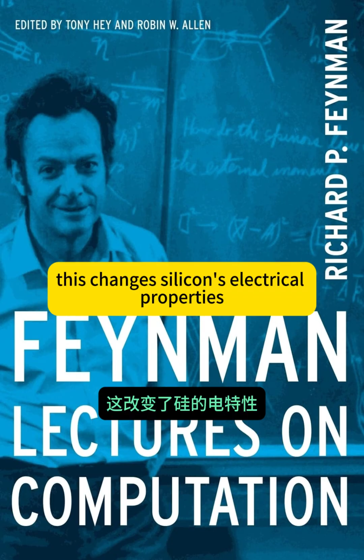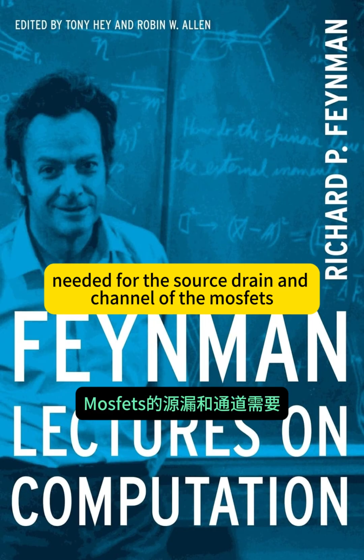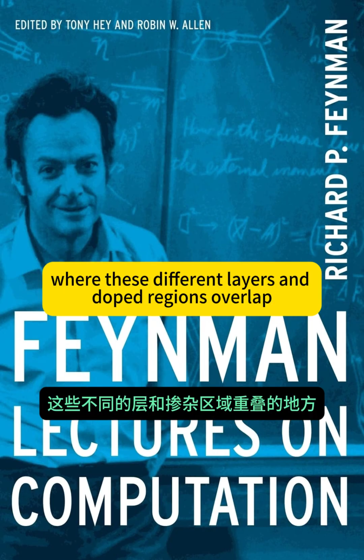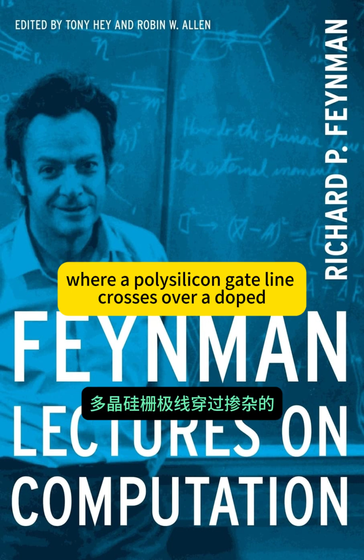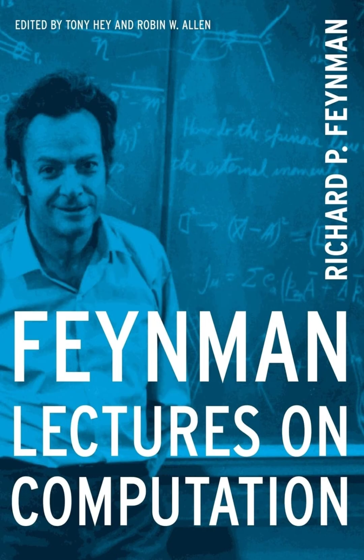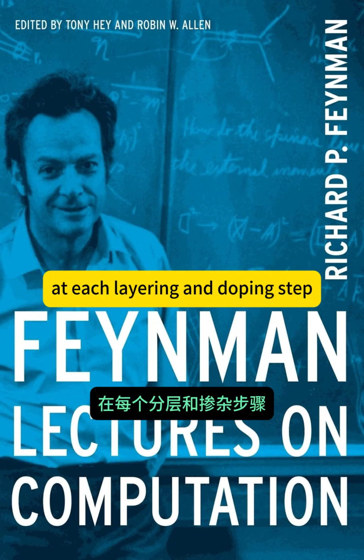This changes silicon's electrical properties, creating the N-type and P-type semiconductor regions needed for the source, drain, and channel of the MOSFETs. So transistors are formed where these different layers and doped regions overlap in just the right way. Precisely. Where a polysilicon gate line crosses over a doped diffusion path, separated by the thin oxide layer, you get a transistor. It's all defined by the masks used at each layering and doping step.